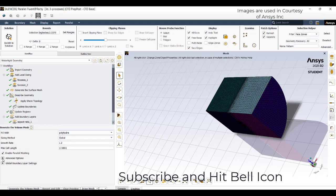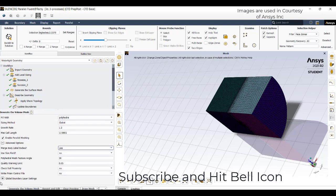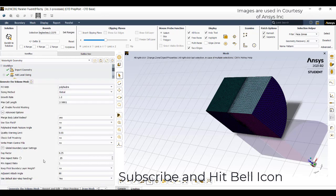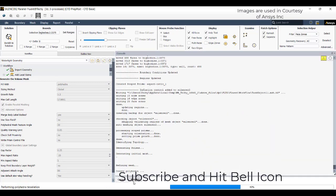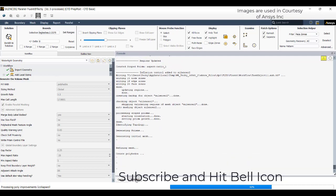And now here you can have a different other options also of giving size field, proximity checking, boundary layer checking, and everything. But now as I'm leaving default, I'm trying to generate the volume mesh. So in this check, the volume mesh is being generated.